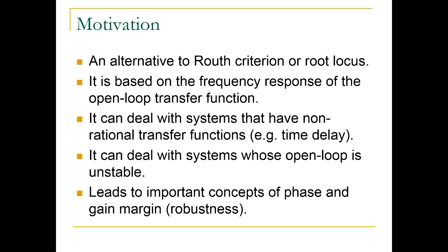Routh-Hurwitz was applied to polynomials, right? So we are checking whether some polynomial has all roots strictly in the left half plane, right? But here, Nyquist can be used for systems with time delay. It can also deal with systems where open loop transfer function is unstable. So it's a very useful, general tool.